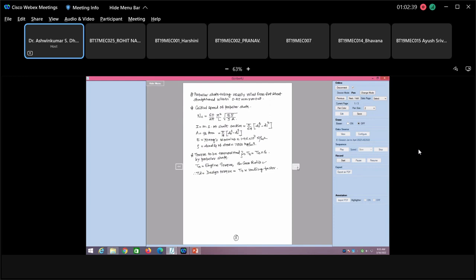Okay, so then from here you can find out TD divided by IP, polar moment of inertia, equals Fs, maximum allowable shear stress, by Y. Y is the distance of outermost fiber from the neutral axis. So you can also find out TD using this equation, Fs IP by Y. If Fs is the allowable shear stress limit for the shaft material, this is known.